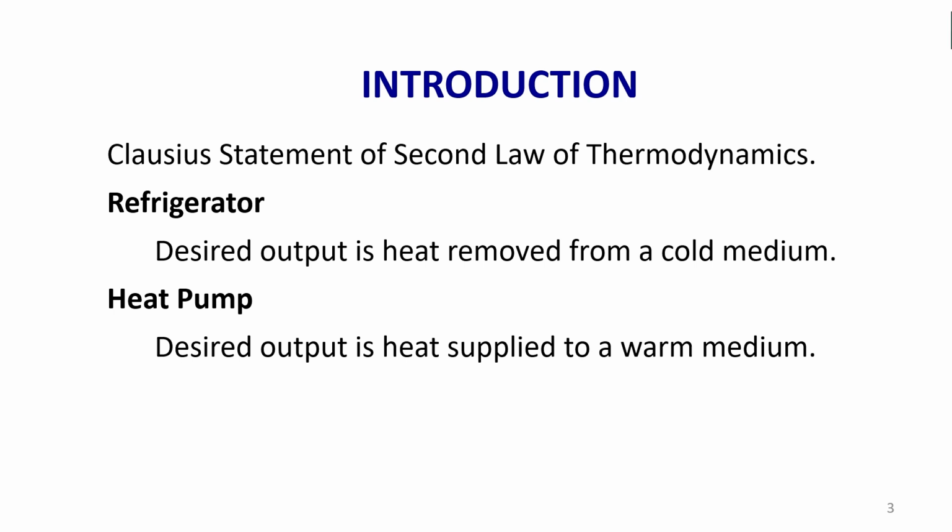In case of a refrigerator, the desired effect is the amount of cooling which is produced, the refrigerating effect, that is the desired output. Whereas in case of a heat pump, it is how much heat has been extracted and rejected to this one. So that is the desired effect of a heat pump. The COP of a heat pump is equal to COP of refrigerator plus 1. We have done this small derivation in one of the earlier lectures.